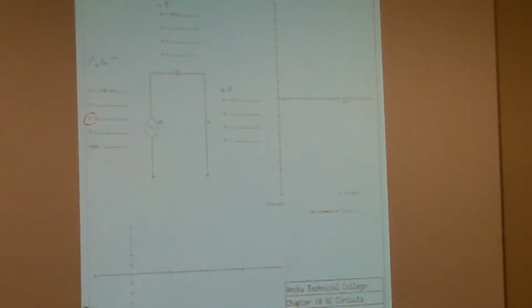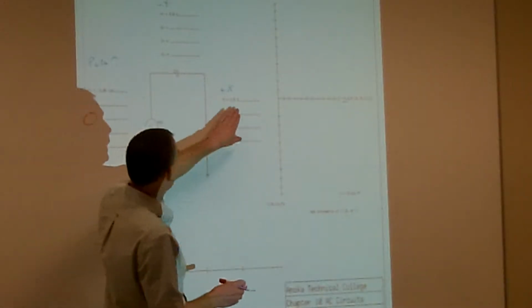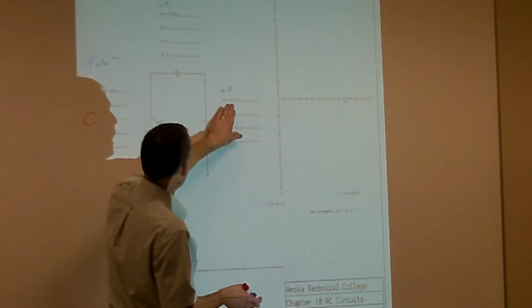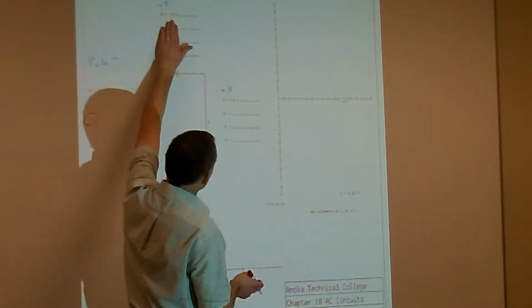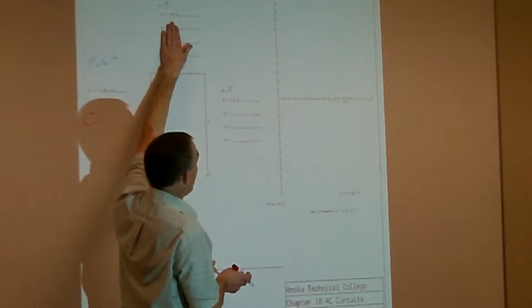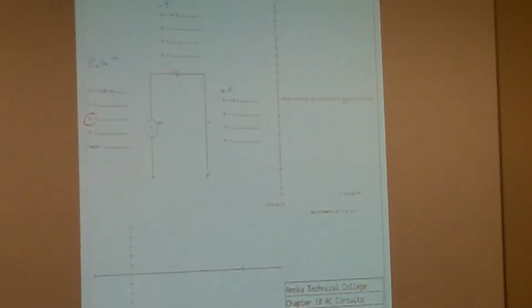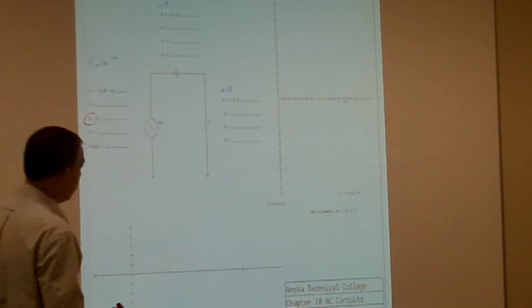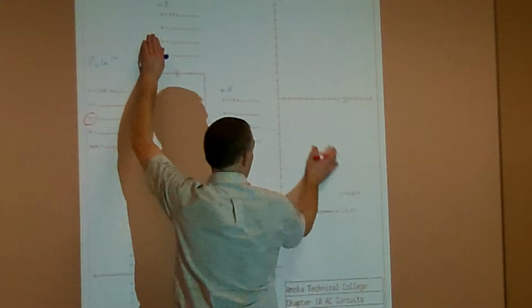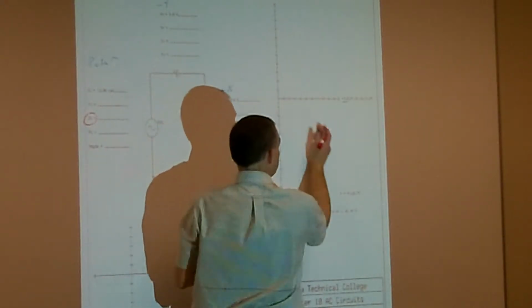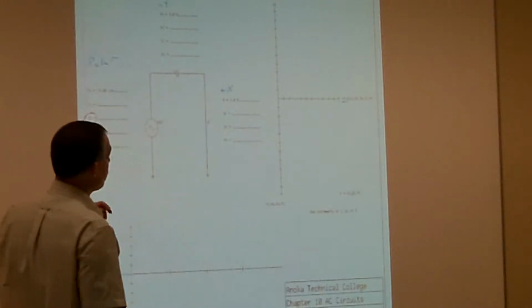So using your rectangular to polar function, what you're going to do is hit in 3 kiloohms, hit your second XY, put in 4 kiloohms, that's going to be your negative Y, and then you're going to hit your second and go to rectangular to polar function. And what's going to happen is that we know that we're going to be in quadrant number 4, and we're going to get some angle and some length on that line.